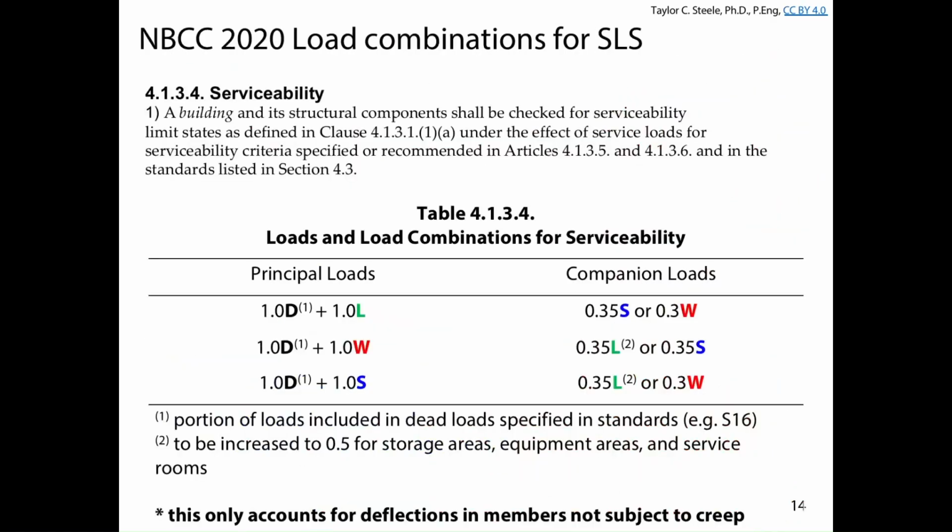So how do we figure out what the deflections are going to be? Well, we're not using factored loads like 1.25 dead plus 1.5 live. We talked about why that is in lecture 10. We factor the loads up higher when we're doing safety checks because we want to make the probability of collapse or partial collapse or somebody becoming injured or killed very low. But when it comes to calculating deflections, what we're trying to do is prevent delamination of tiles, prevent cracking of tiles, and make floors not too bouncy. Different levels of acceptability, right, in terms of the building's use.